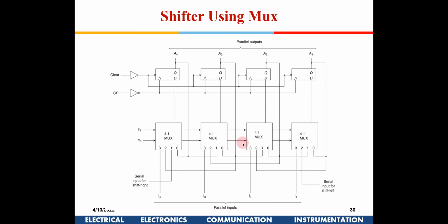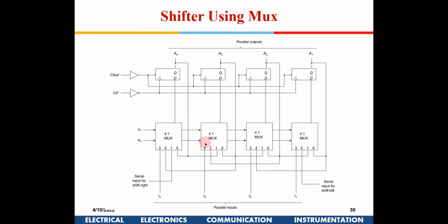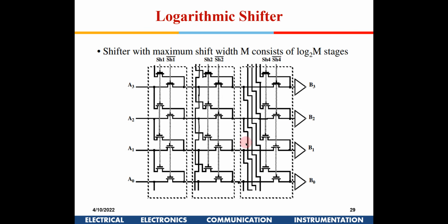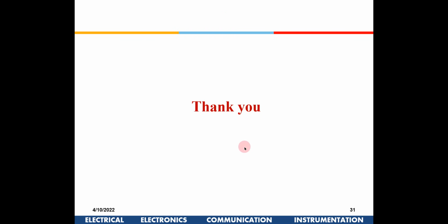So you see again, as the clock frequency is going high, we can start using sequential circuits, replacing some of the combinational circuits. So this is doing the same function as that one. It requires much less space here, because this is much simpler, and this is only a shift in one direction. If you have to do it in two directions, you can imagine the complexity, whereas these circuits are pretty simple.